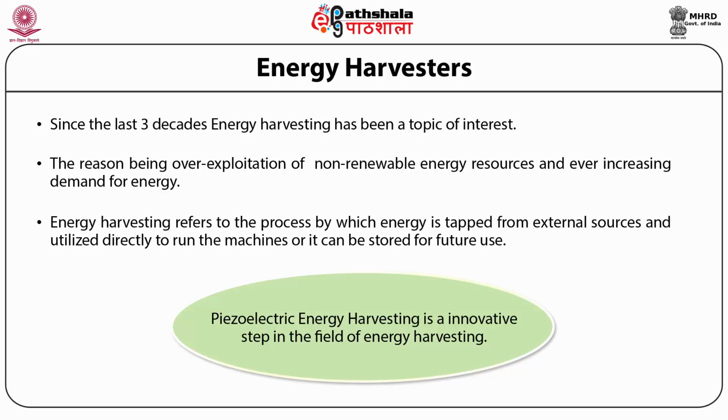Solar farms, wind farms, and tidal energy farms are some traditional energy harvesting techniques. An excellent commercial example of energy harvesting is the recent system being developed by Perpetuum, which converts the vibration of rolling stock into electrical power for the wireless communication of sensors that predict the failure of rail wheel bearings. The ability to deliver sustainable power to a wireless system network by energy harvesting is attractive not only because of the cost of batteries, it also removes the additional time and cost necessary to replace and maintain the batteries and the labor required to install complex wired systems.